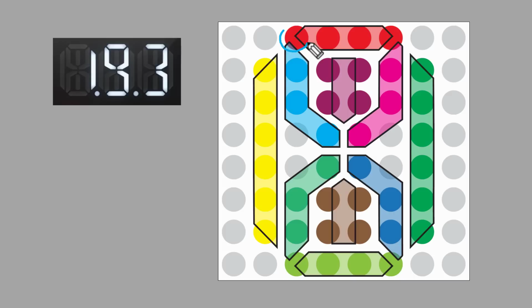The first exception are those four corners, because those LEDs are being occupied by two segments, actually just a tiny portion of this segment. So I think that what we can do once we print the 3D diffuser is to just change the shape slightly to not include this part of the LED. And the second problem are those middle pieces which are not perfectly aligned with any of those LEDs. But thankfully, since we can use 4 of those LEDs for those segments, I'm hoping that enough light will be able to get into those segments to make them bright enough.